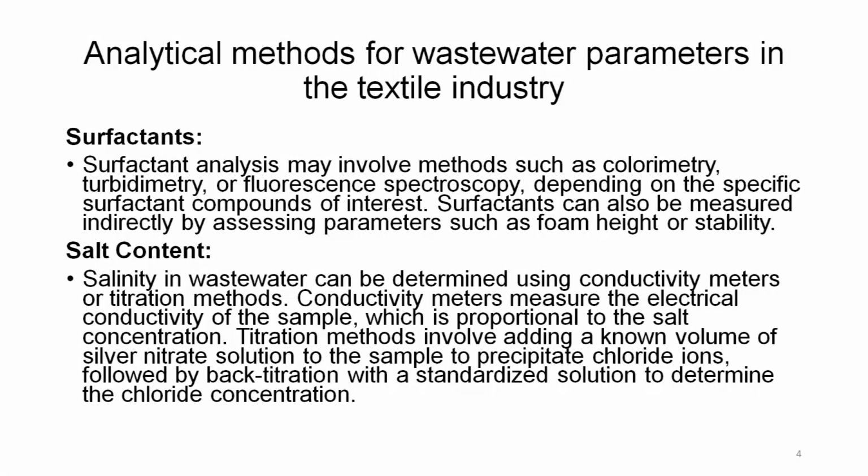Similarly, the pH can be determined by pH meter, and surfactants can be determined by turbidometer or colorimetry, or even by use of fluorescence spectroscopy. Color can be determined by spectrophotometer, that is color scan machine, and at a proper wavelength the quantity of the dye can be determined. Similarly, salt can be determined by titration method or by conductivity meter.